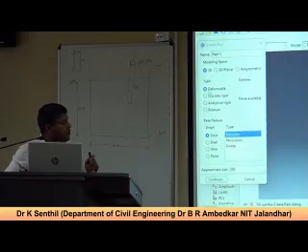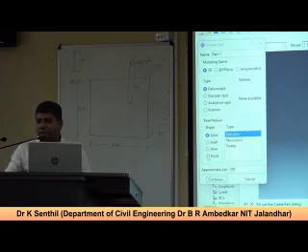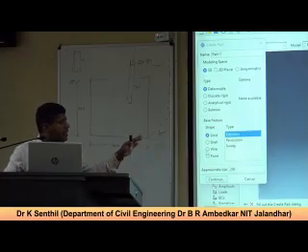Okay, so now let's talk about the deformable, and further you can see the base features like shapes, whether it is a solid element, shell element, wire element, or point element. It depends on the degrees of freedom you have. What type of element, whether it is a bending element, or a wire element where there is no bending, like a beam element or truss element, right? All this you can select any one.